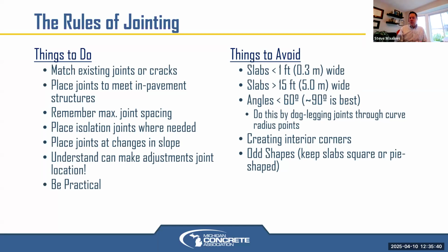Granted, FAA has their own design guidelines for joint spacing. It's based on the taxiway width or the runway width, and then to that maximum, but they'll divide it out equally. So we generally see a lot of 18.75 foot panel sizes at airports because of the runway or taxiway widths and the maximum thicknesses that they allow to control cracking.